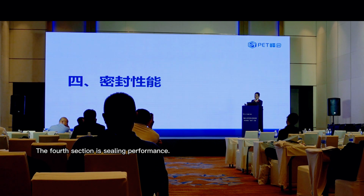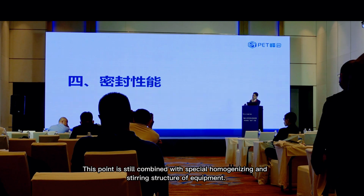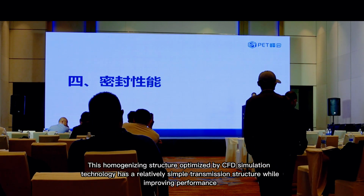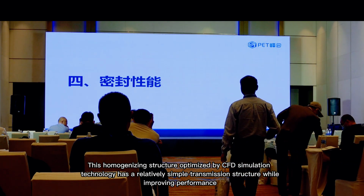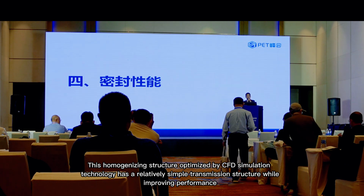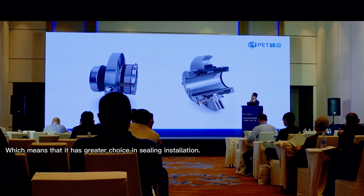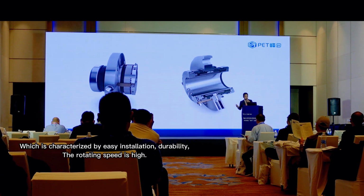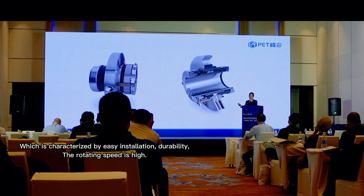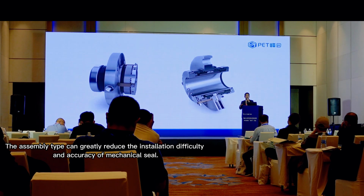The fourth section is sealing performance. This point is still combined with the special homogenizing and stirring structure of the equipment. This homogenizing structure, optimized by CFD simulation technology, has a relatively simple transmission structure while improving performance, which means that it has greater choice in sealing installation. We have selected this internationally advanced sanitary cartridge mechanical seal, which is characterized by easy installation, durability, and high rotating speed. The assembly type can greatly reduce the installation difficulty and accuracy requirements of the mechanical seal.